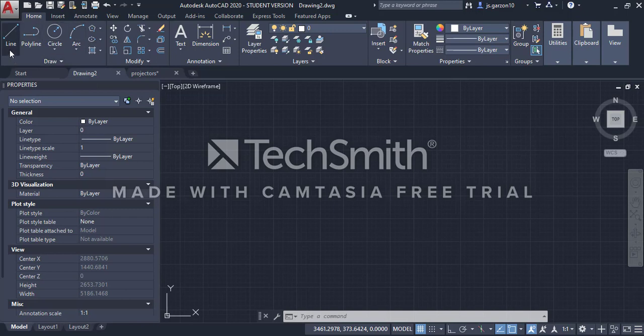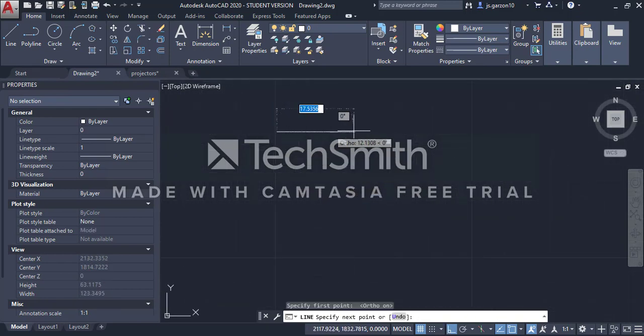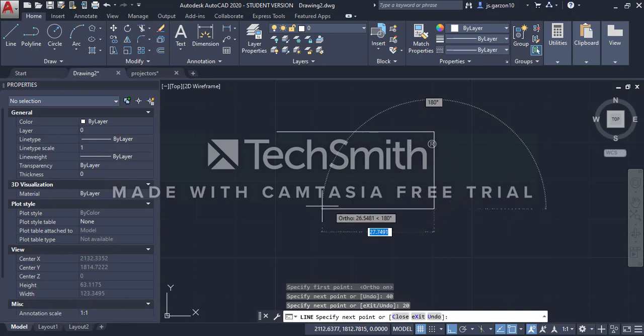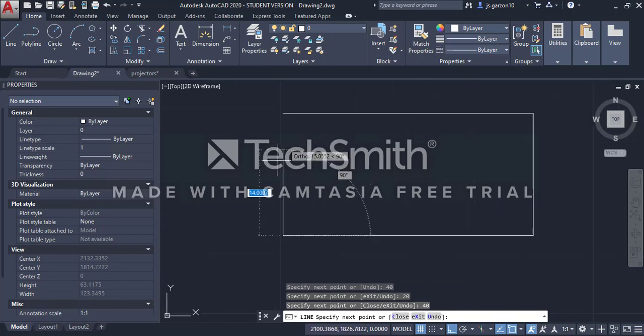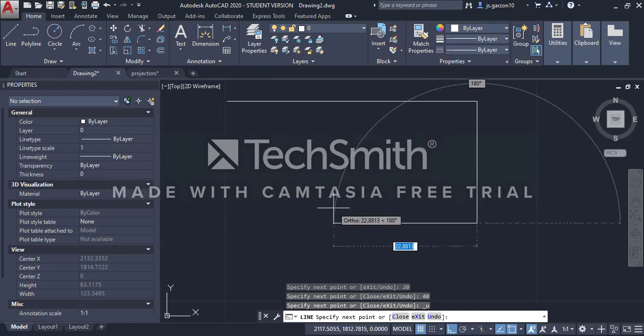So, the difference between a line and a polyline is that a line is not continuous and a polyline is continuous. So if you draw with a line, and if you want to draw in 90 degrees, you can specify 40 millimeters as an example, like 20 and 40. However, if you don't want to specify in the last part the 40, you can just Ctrl Z and it will return you to one step before clicking.